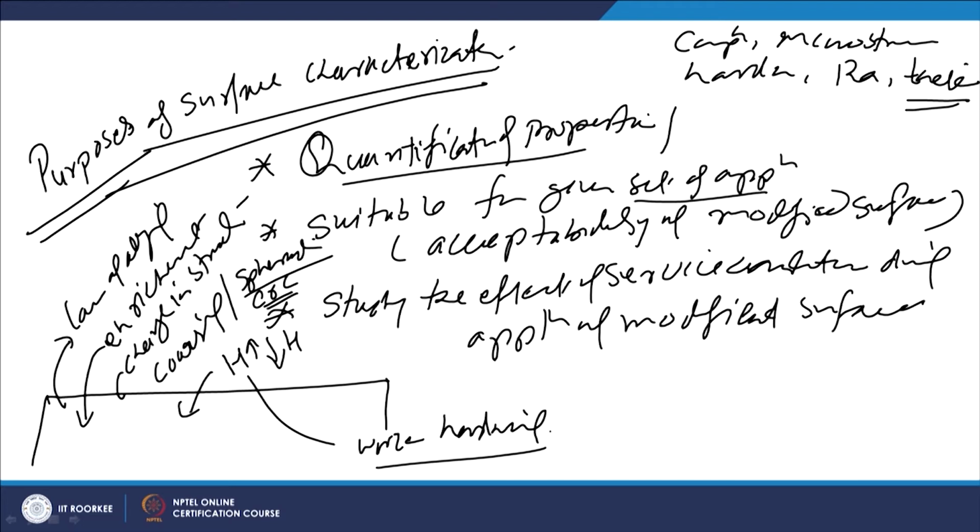There can be a reduction in hardness as well if there has been destabilization of the microstructure micro constituents which were contributing to the required hardness, or there can be a loss of alloying elements from the surface leading to a reduction in hardness. So, the chemical composition modification or the microstructural modification can lead to both hardening or softening.